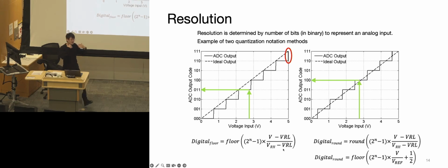When an analog signal is coming in, we don't necessarily know its ground or the reference of the signal. The high and low you set give the sampling range of your ADC channel, so this is the range that all those bits of resolution are divided into.